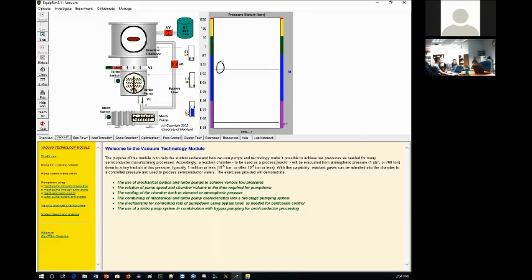Norfolk, are you guys with me? Were you able to follow so far? Wonderful. Okay, so this just showed you how to carry out a process. So as easy as that. Mechanical switch and mechanical pump. Then we pump down the reaction chamber, close this valve, open the, this would be called the foreline valve, right? The valve connecting the mechanical pump to the turbo pump. That will be opened up, and then the reaction chamber is at very low pressure too. We are ready to do, say, evaporation at this point. Okay, so things worked out pretty nicely.